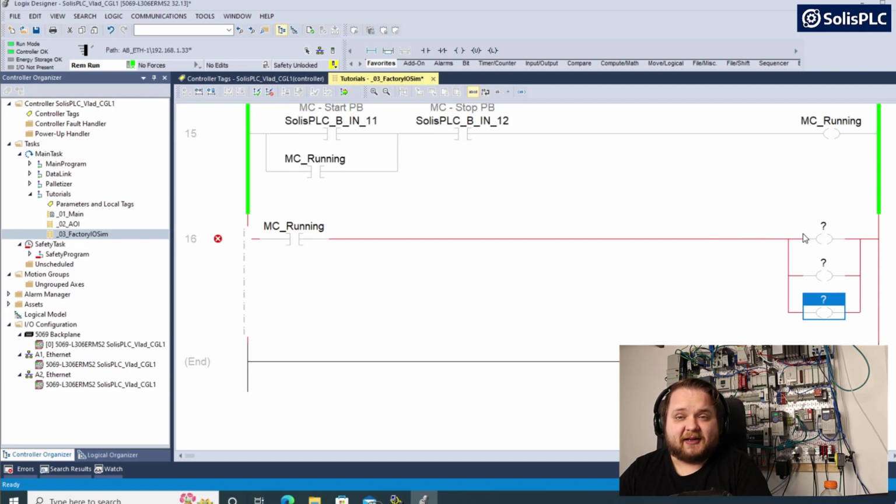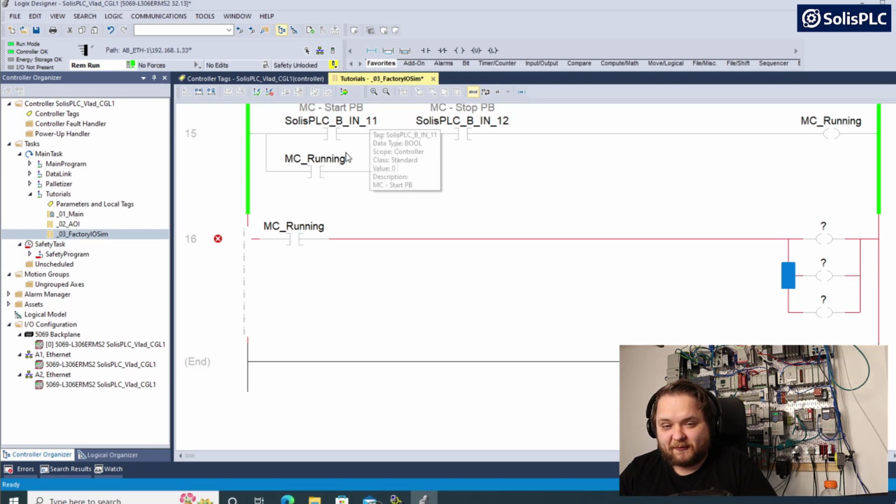That being said, if I'm asking this question of an automation engineer or technician, I would expect them to mention that nuance. I would say, well, what if I add a condition here versus if I add a condition in series? In that case, it's going to be different because here the condition is only going to impact this branch, while if it is in series, it's going to impact everything that is set after it. But in any case, that's going to be a little trivia for you guys.